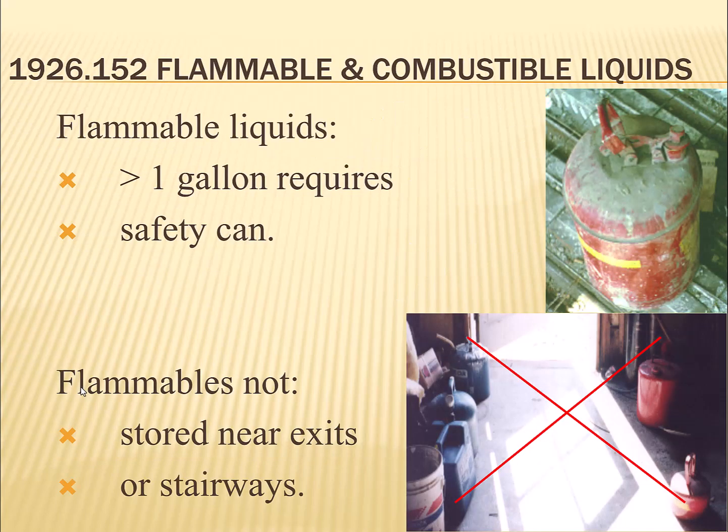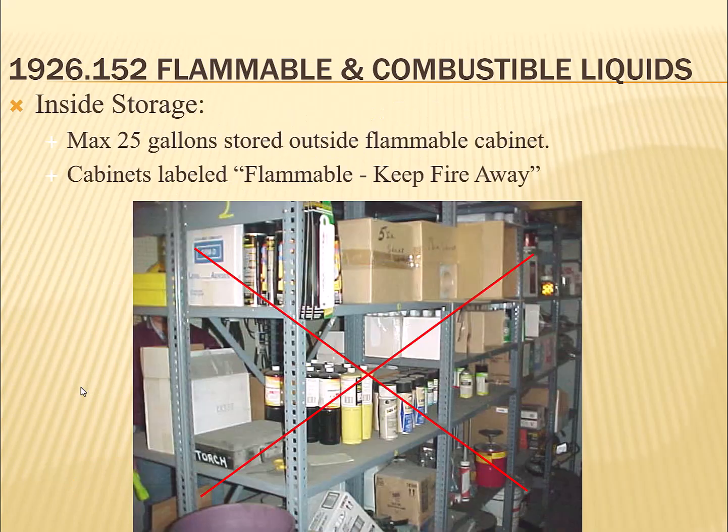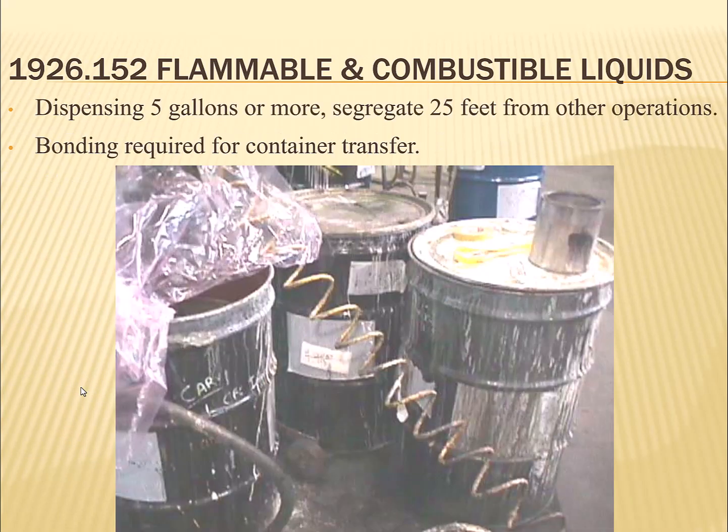Okay, well, beyond that, some of this is a bit of a repeat, about the idea of the flammable liquids and bonding required as you're fueling from a container like this to your fuel can. That means an electrical wire clip to both containers, so they're electrically connected. Or, like with your car, when you fuel up, you've got a metal receptacle in the gas tank housing when you open up the gas tank, and a metal hose, so that they electrically connect with each other. So they are electrically connected when you start fueling to reduce the static charge hazard.